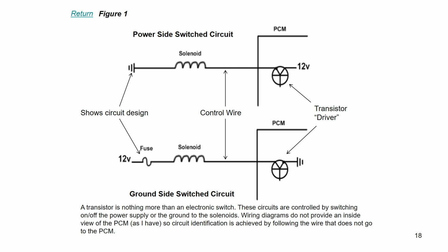So power side switch we already covered. This is the guy that we talked about previously with the fuel pump circuit, right? Circuit off, my voltage here and here, let's do 2 measurements, would be what? Driver is off. What are we going to see on those 2 guys? Good, 0 and 0. Driver off on this device, this is a ground side switch circuit. Externally powered means it's internally grounded. This bottom one's ground side switch.